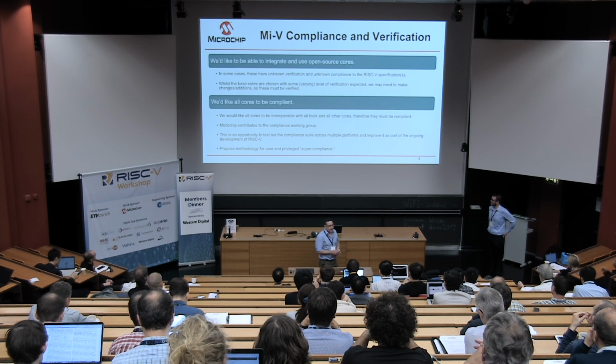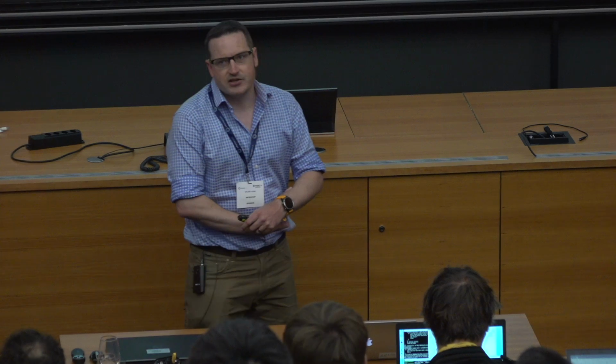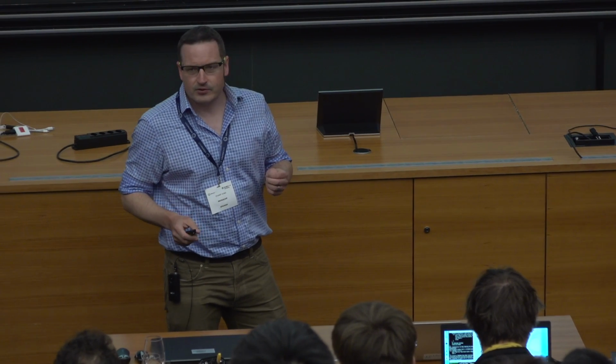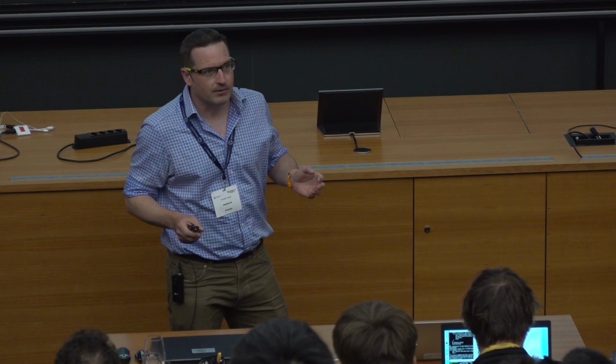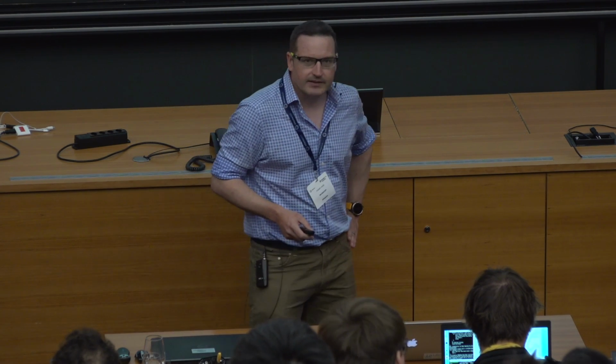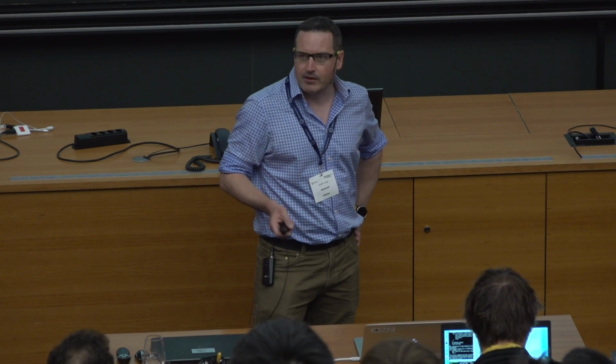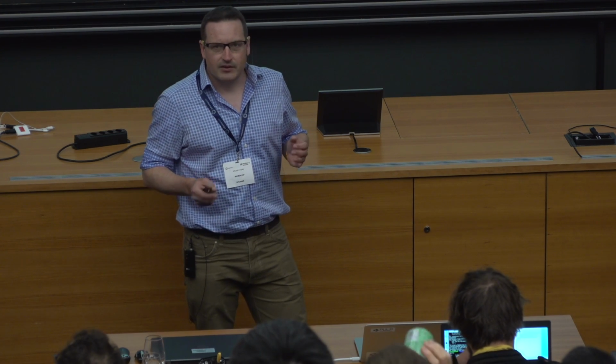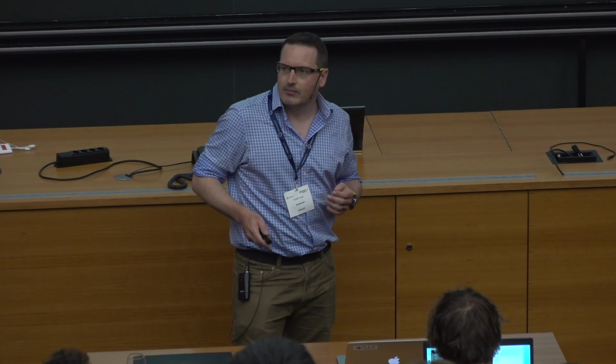We also, as I say, in our early days in RISC-V, looked at the deficiencies in verification in RISC-V, and we're thinking about how to address that. Because realistically, it's very difficult to achieve the verification quality of someone like ARM, because they have a lot of history in building processor cores, they built up a huge amount of verification IP, and they have a huge amount of resources to apply to the verification problem. So how do we apply modern techniques like formal methods to try and achieve a similar verification quality in a much shorter time on RISC-V?